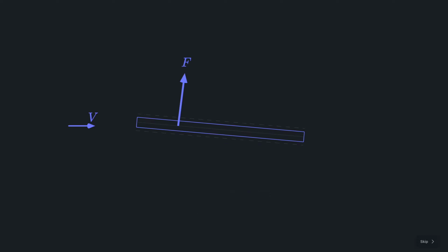There is another explanation of lift based on Newton's laws. As air flows around the plate, it gets deflected downwards. According to Newton's second law, this requires a force applied to the flow by the plate. Thanks to Newton's third law, the plate experiences an equal and opposite force. We can break it down into two components, one that acts vertically, which we call lift, and another that aligns with the airflow direction, named drag. Even a simple plate can generate lift, albeit with a trade-off, in the form of substantial drag.